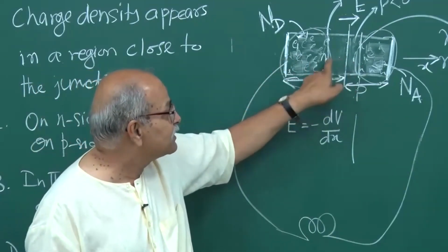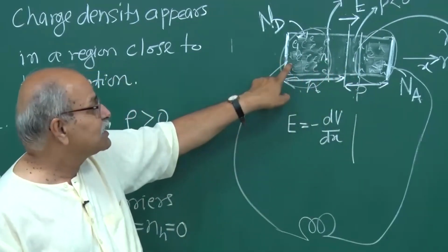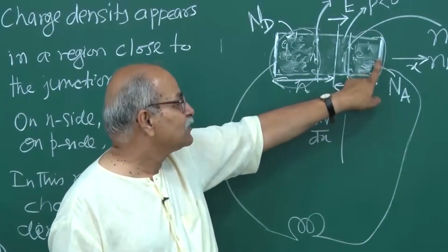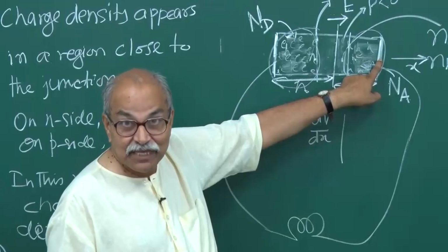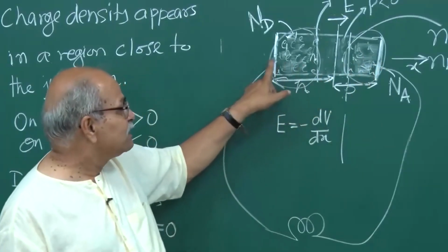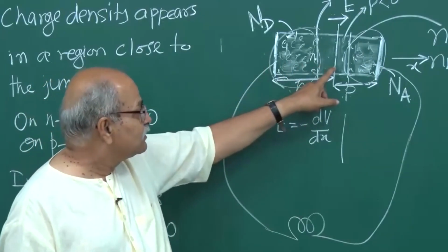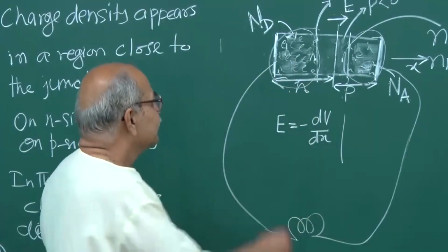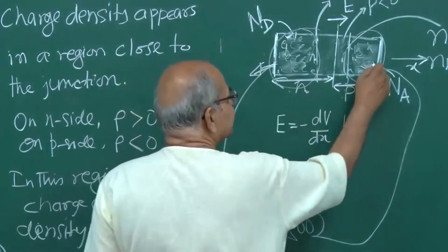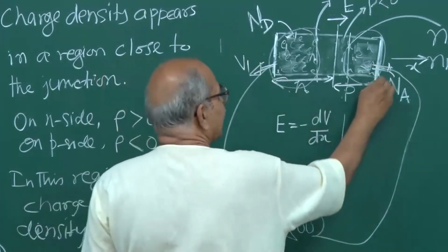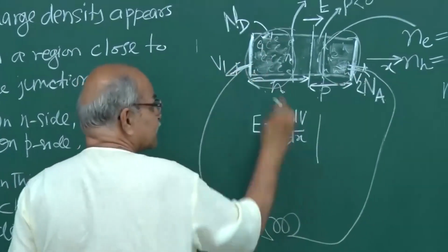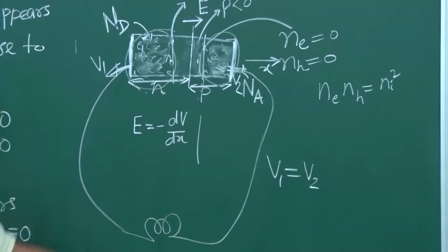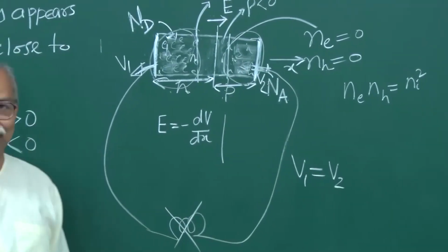As you have a potential difference across this junction, you also have a potential difference across this junction, and similarly across this junction. So here also, semiconductor to metal, there will be a contact potential difference. When you sum all these things, this potential finally is the same as this potential, V1 equal to V2 after those metallic contacts, and so this bulb is not going to glow anymore.